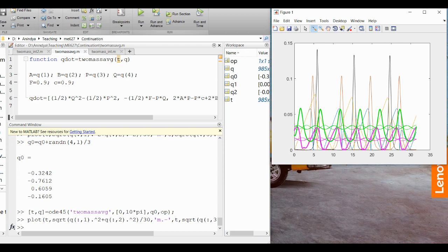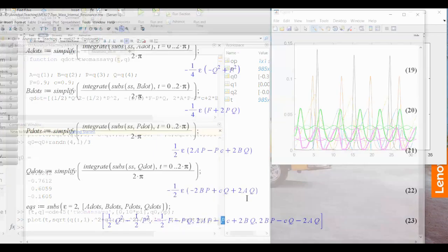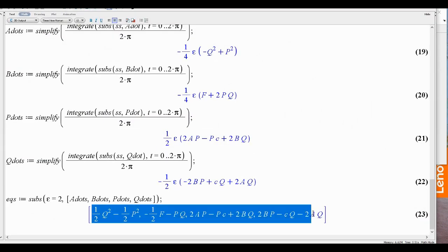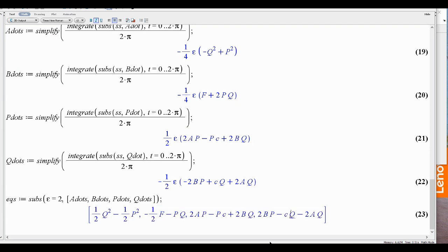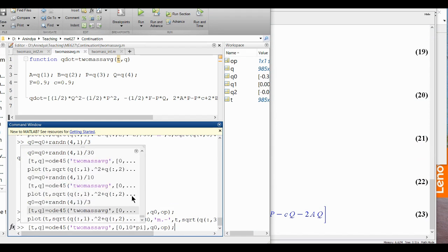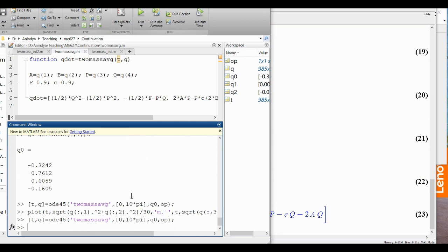One, you may say, if I am solving it numerically, what is the use of doing it? Well, you see, this does not have a sine omega t and a cos omega t. The numerical integration proceeds much faster. I am integrating over a shorter period of time, getting the result almost instantly, right?